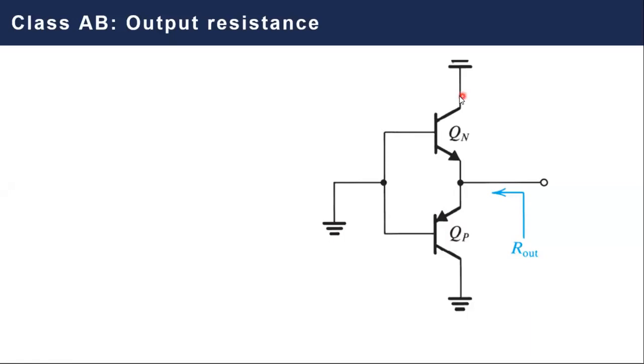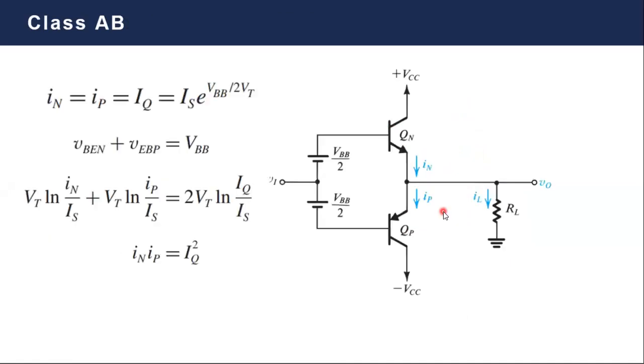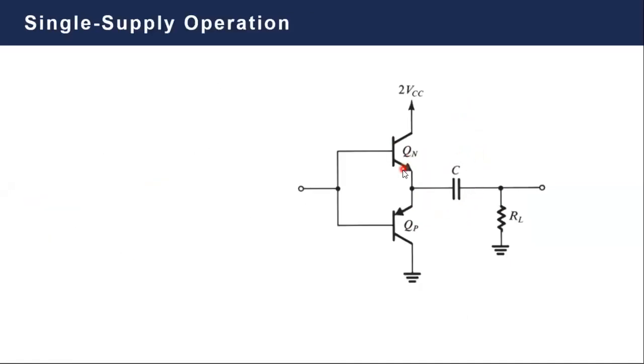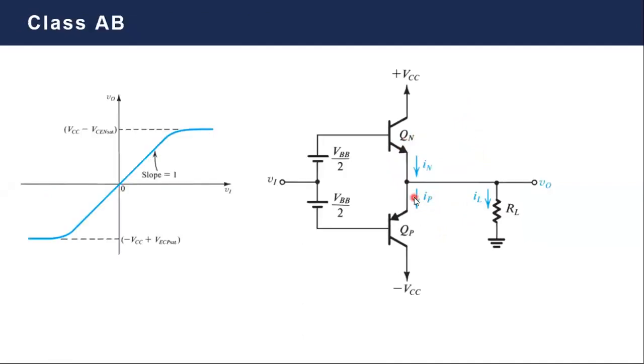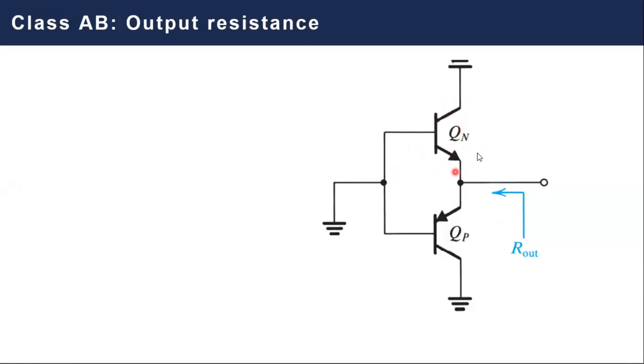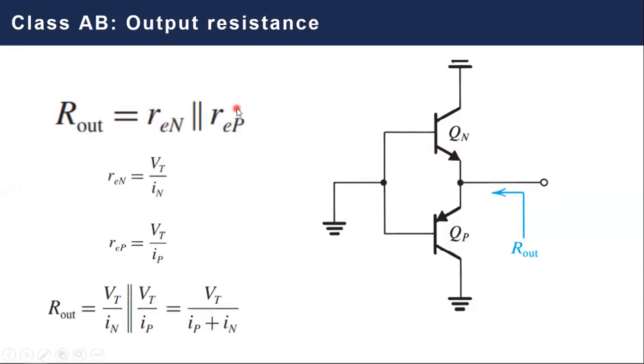The output resistance seen by a class AB amplifier is typically the same as the output resistance seen by a class B amplifier. That's why we can merge this calculation once for both. Here, the output resistance can be analyzed in terms of what we call the small-signal resistance, which, if you remember from your Electronics 1 or Electronics 2 classes, is small re.